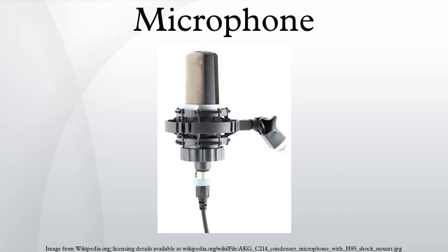The RF biasing process results in a lower electrical impedance capsule, a useful byproduct of which is that RF condenser microphones can be operated in damp weather conditions that could create problems in DC-biased microphones with contaminated insulating surfaces. The Sennheiser MKH series of microphones use the RF biasing technique.